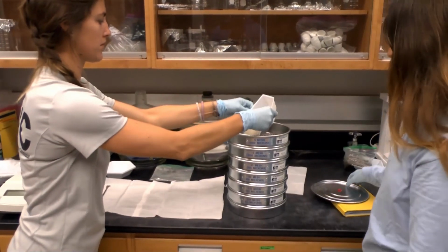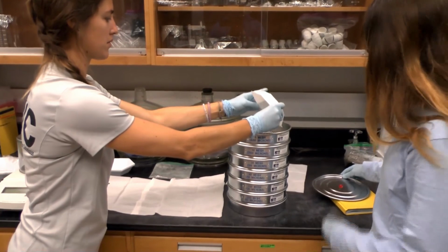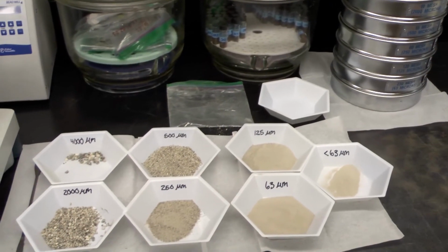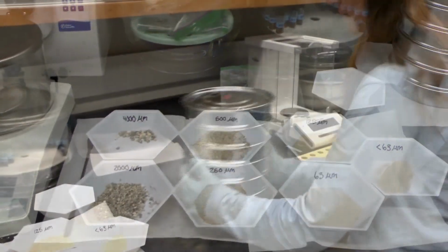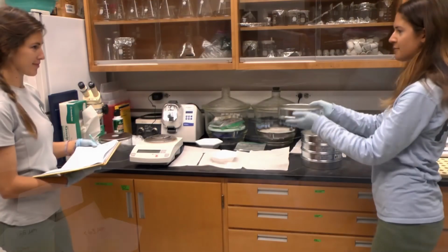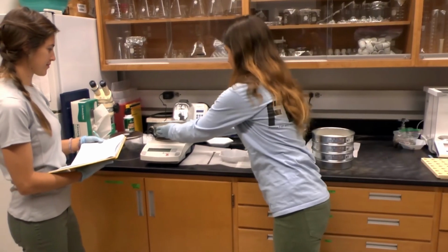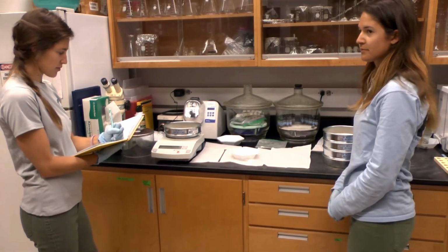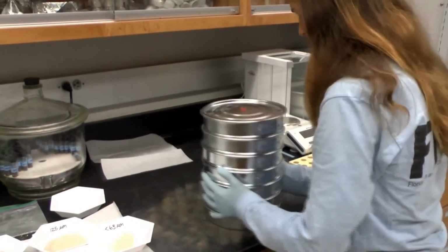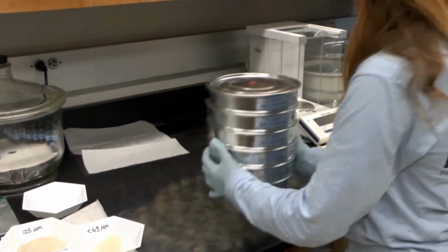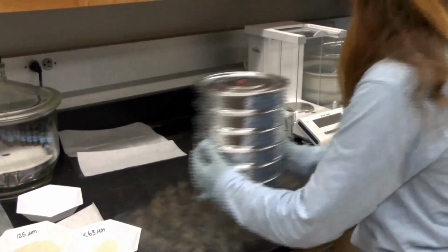Place the sample in a stack of pre-weighed sieves that are ordered by mesh size. This will separate out the sediment into various grain sizes. After shaking the sieves for 3 minutes, manually or with an electric sieve shaker, remove one of the center sieves and record the weight. Then replace the sieve in the stack and continue shaking for an additional minute. Weigh the same sieve again and repeat the process until the weight remains stable and the sample has completed separation.